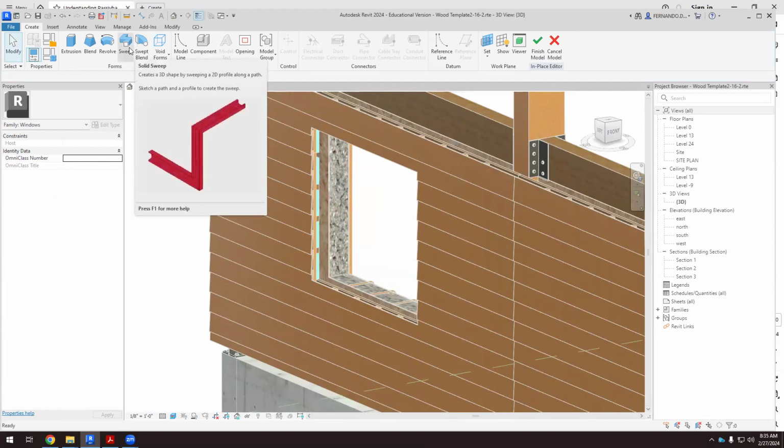Okay, so we have to create a shape, we have a path, and we have to build, or move or extrude, that shape along the path. We can use extrude when we have a line, but when we have something that is not a line and we want it to follow a weird path, then we have to use the sweep. So we're going to use this many times. At the end of today, I think you will internalize this option of sweep.